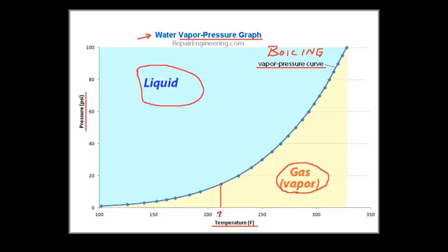For example, many people, when asked if they know the boiling temperature of water, will answer that it boils at 212 degrees Fahrenheit. This answer is partially correct. As shown by the graph, water does boil at 212 degrees Fahrenheit at the standard atmospheric pressure at sea level of 14.7 psi. However, notice that the boiling temperature of water changes with its pressure. In general, lower boiling temperatures correspond with lower pressures, and higher boiling temperatures correspond with higher pressures, as we can